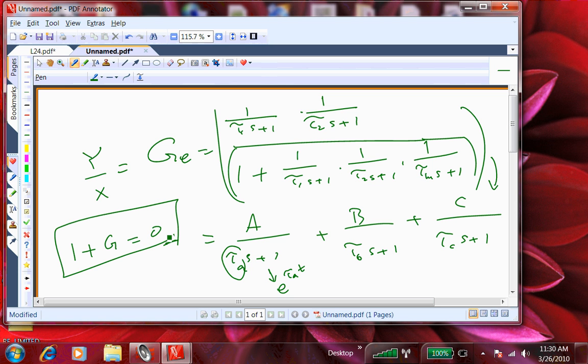That way I can know whether it's stable or not. Okay? So really, all the ideas that we have seen, we are going to be applying in different ways. And one of the things at this stage that you need to be able to link is that the stability of this combined feedback system is determined by the characteristic roots of the denominator of that effective transfer function. Am I making sense? Okay.